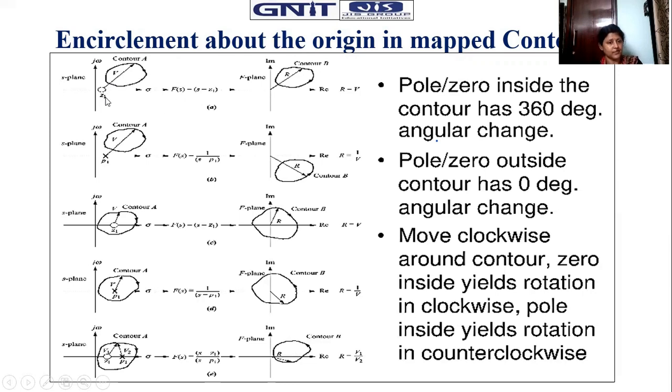Okay. So the point of singularity means the given pole positions, so we must avoid those pole positions, because it will break the control, right? If we put the value s equals p1, the function will become infinite. So there is a discontinuity, and that should be avoided. So the point of singularity is an important concept here also.